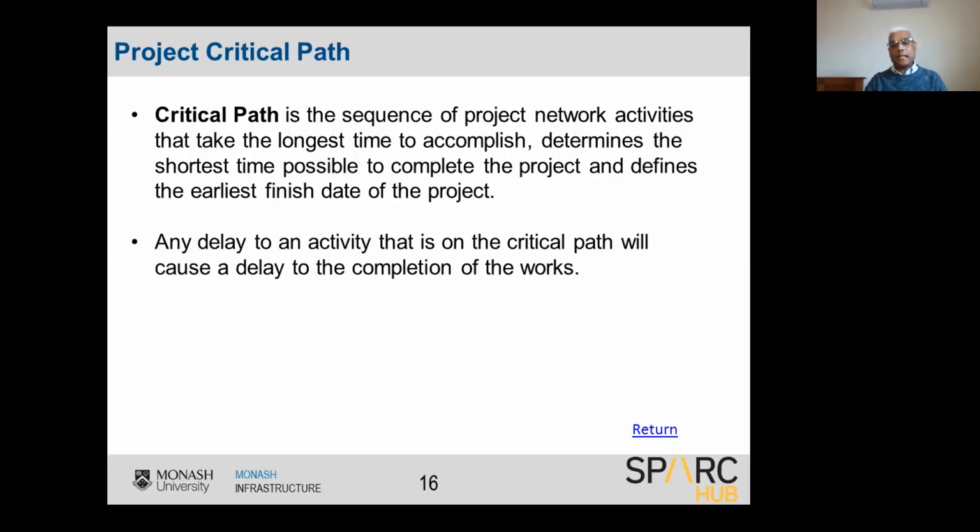Any delay to an activity in the critical path will delay the project. For example, assume that the critical path is the factory manufacturing and fabrication of the columns. At the site, if there's a delay to the foundation work, the concrete work or the site clearing, it will not delay the project because you will have a float. We call it float. You will have enough time to recover until such time the columns are delivered to the site.